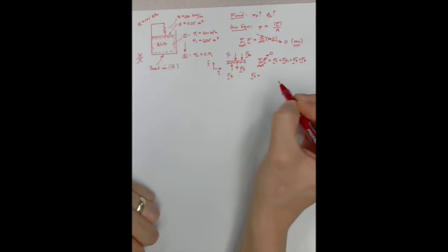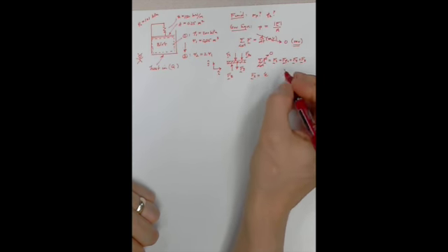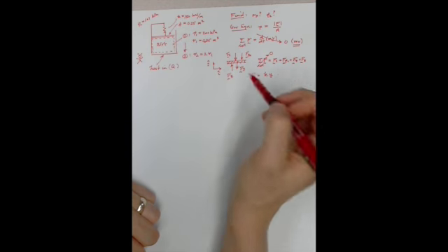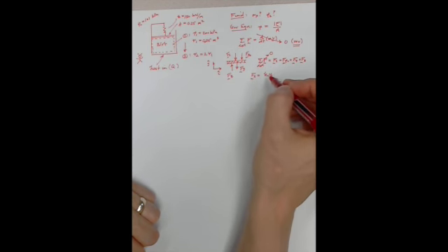So for instance, the force of the spring, you remember from physics, looks like a restorative force. So some linear constant from Hooke's law multiplied by some displacement, let's call it y, since we're going to be displacing up and down here. And then we need a direction to add to this. And even more importantly, we need to define this coordinate y.